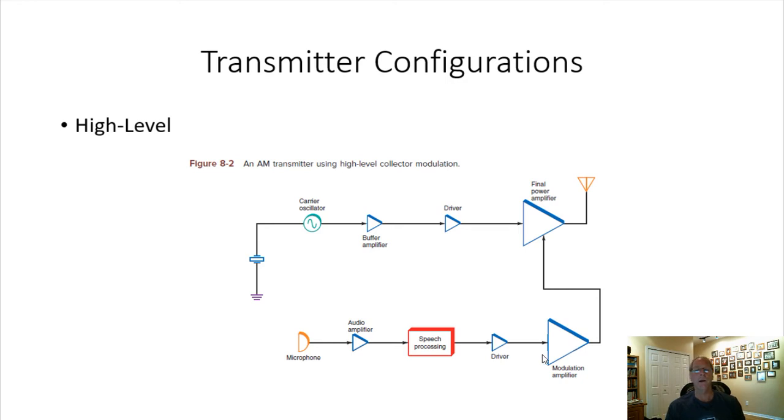All right, so AM transmitters are normally high level, and you know what happens when you overmodulate an AM waveform, right? We saw that in our first lab, you get that distortion. Here's a carrier oscillator. It's crystal controlled. So that final power amplifier is the part where the modulation occurs. It doesn't occur over here.